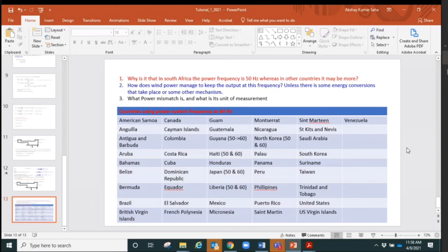But if you are operating at 0.8 and still you want to go to the rated value of voltage 1.0 per unit by increasing the excitation, that will increase the reactive power, but that will drop the power factor, which you cannot possibly afford. So in that case, you will have to do something else. What you can do, you can use a capacitor bank on the load side to boost the reactive power and the voltage of the buses, meaning you have reached the limit of your generator control.